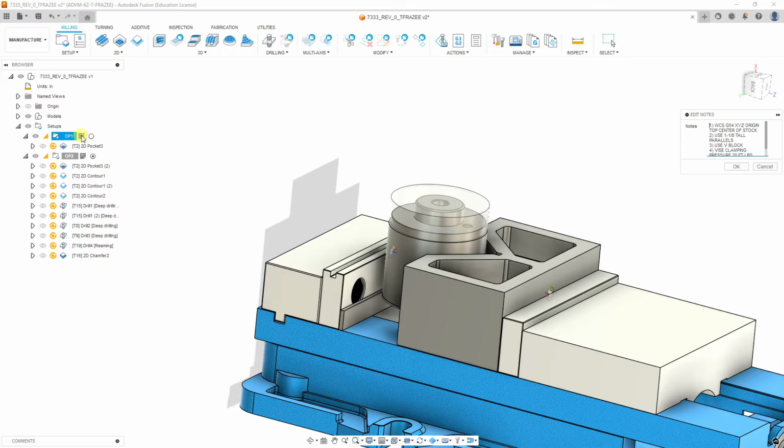Now let's fix our notes. This note is all valid except for the parallel height. So we're no longer using inch and 5/8. We're going to use 5/8 tall parallels. So let's fix both setup sheets. Okay, there we go. Let's save again.